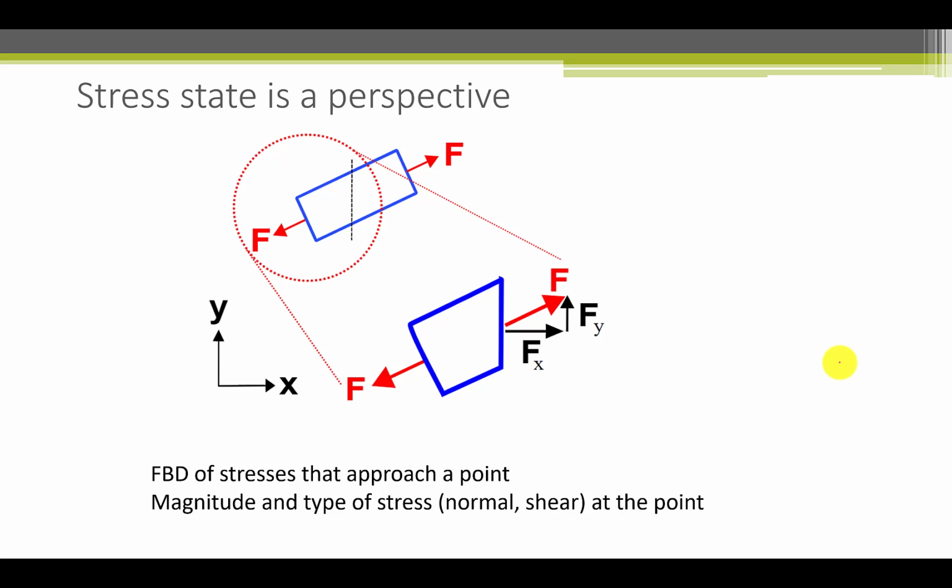So far, we have taken the free body diagram cut plane normal to the force acting in the axial direction of the rod. But we can take a cut plane at any angle we choose, for example, this plane, which is at this angle to the axis. Now something very strange emerges. With respect to this new plane, there is now not only a normal stress, but a shearing stress as well, indicated by decomposing the axial force, the uniaxial force, into its directional components along the new coordinate system axis.